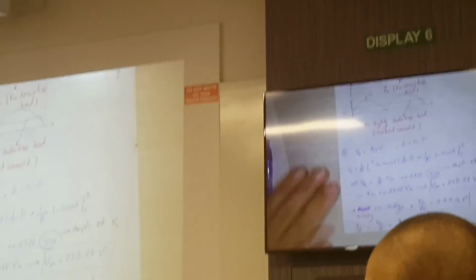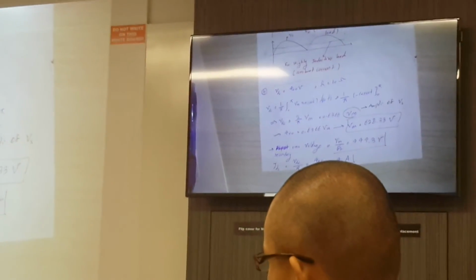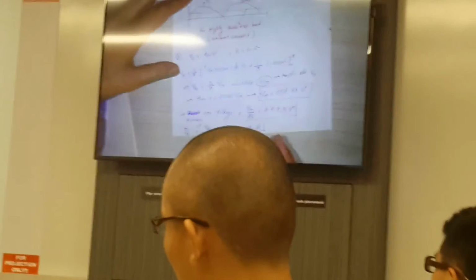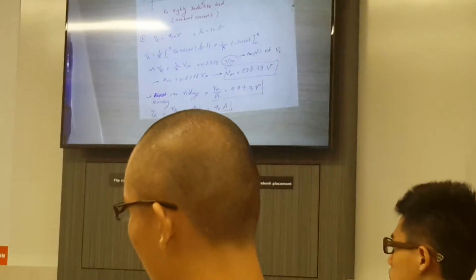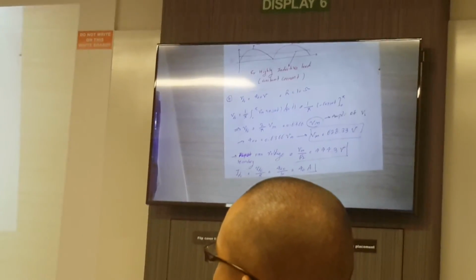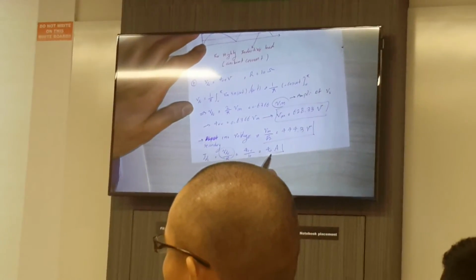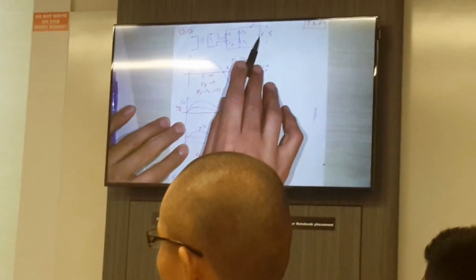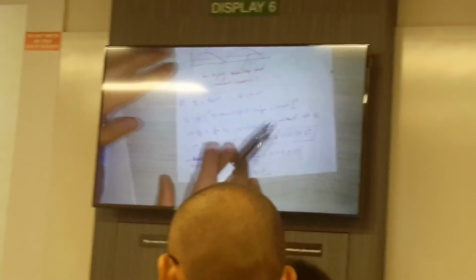28 volts. So if you want to calculate the RMS voltage, Vm is the amplitude, and the RMS will be Vm over root 2. On the other hand, if you want to calculate the average output current, since we have the average output voltage, the average output current will be the average output voltage over R. This one also I have explained previously in the first tutorial. Since the question also gives that the resistance is 10 ohm, the IDC becomes 40 amp.